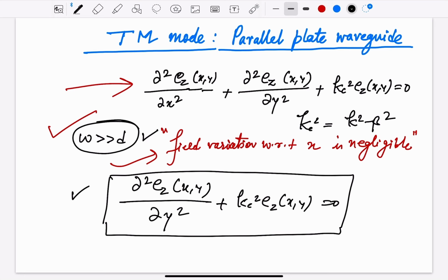Fine. So yes, you can write the cutoff frequency as, in the same sense, actually I'm directly recalling the expression. This was n by 2d under root mu epsilon, and beta is under root k square minus kc square. Fine. So you can write these things, k under root in terms of the cutoff frequency, which is fc by f to the whole square. So it's a very important role here, this cutoff frequency. We are defining all the things.